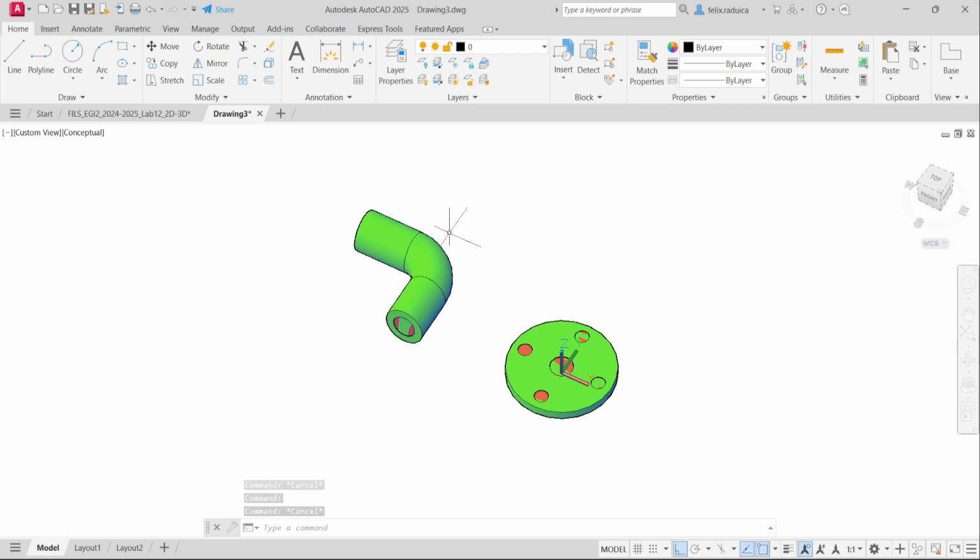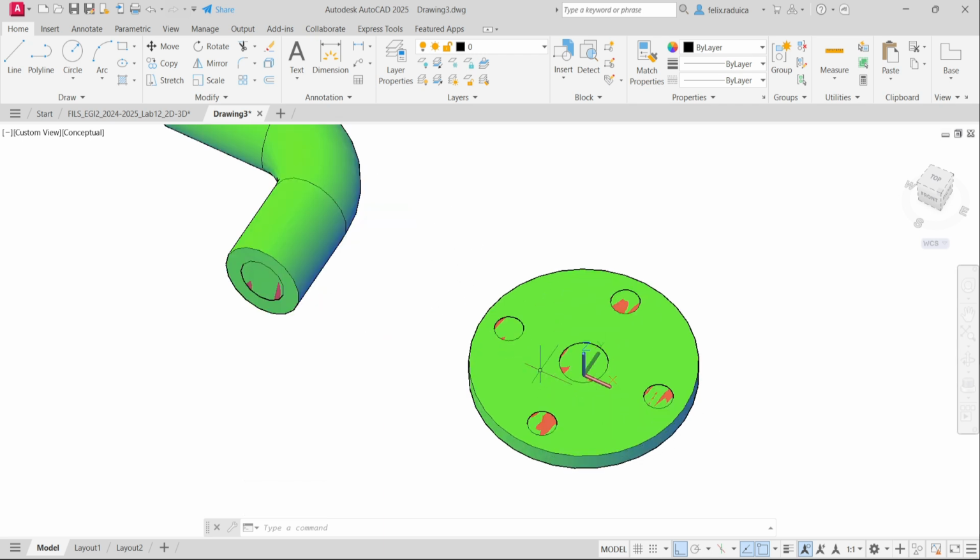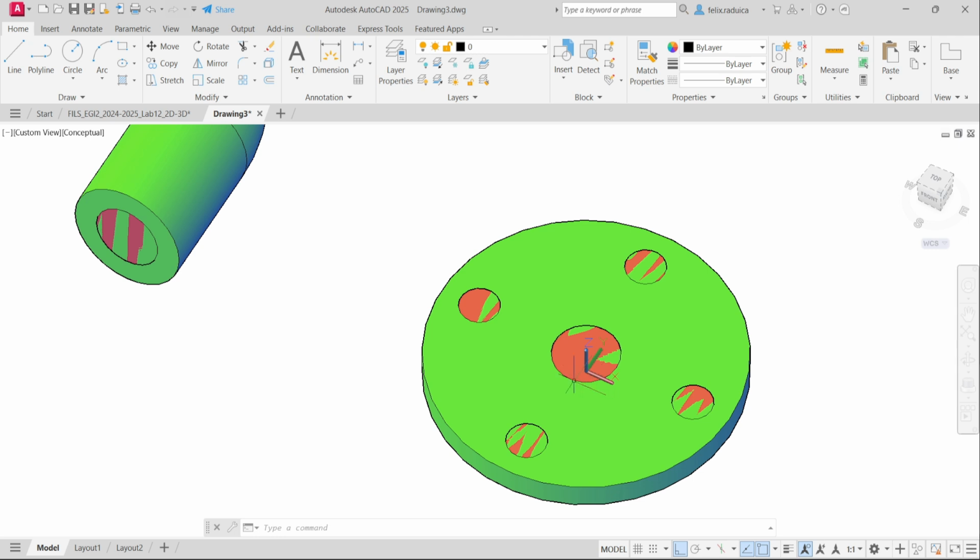Okay. And now this flange here has an extra part, an extra geometry. If I extrude this, subtract this from the flange, it will have the holes. But these, because I drew them so that they are supposed to overlap so they can join with the flange. So I don't really need this inside geometry cylindrical part here. I can delete that one because this one will overlap with this face here.